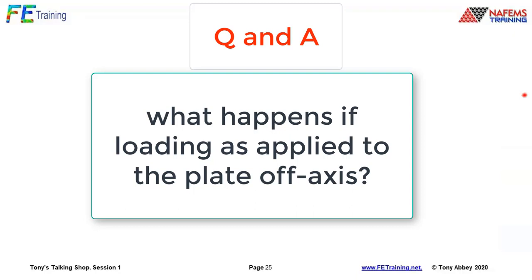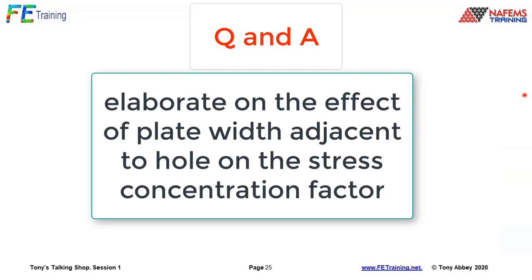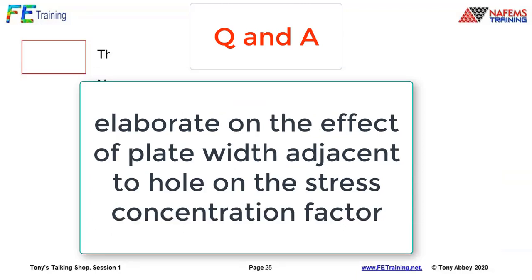That's an interesting question. Mira asks, can you please elaborate on stress concentration factor of finite plate versus infinite plate of the center hole? What practical scenarios do you utilize both and the selection criteria? Again, a plate with a hole in it is perhaps a rather boring example, but it's a very good example. The point I was making there, here's a plate. We're going to apply an axial load to that. We assume we constrain it on that side. If the plate is wide enough, or the hole is small enough, then we can approach a stress concentration factor of 3.